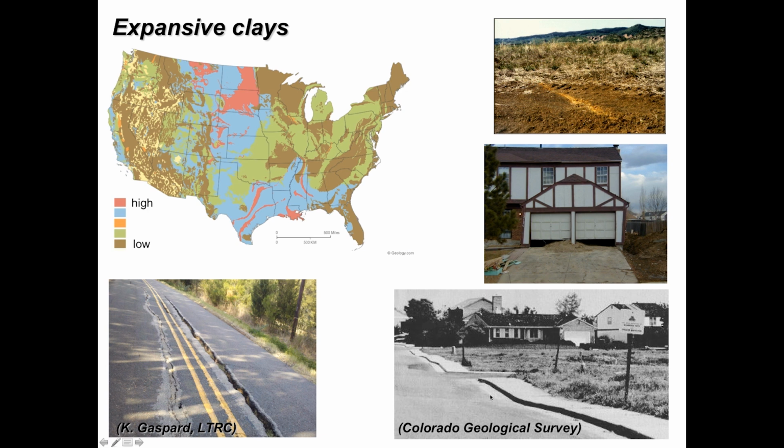And then finally, this photo in the lower right is a fairly typical distress pattern in an area that's underlain by these steeply dipping layers, as we were talking about earlier. And so these heave features along this roadway here really look like speed bumps, and these correspond to underlying thin beds that have been upturned to a steeply dipping angle that are causing this very severe differential movement.